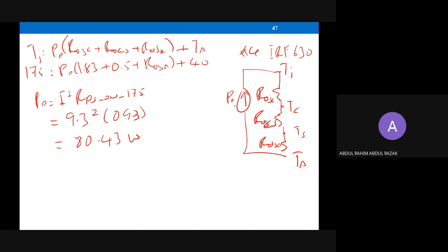So the losses emitted from this device at this point are 60 watts, almost reaching the 62 watts maximum power dissipation mentioned on the first page of the datasheet. We try to find out how big the heatsink should be when 60 watts of dissipated losses happen here.